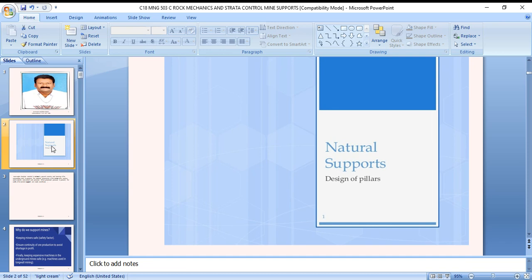The vertical compressive force, the effect of P1, is to compress the rock in a vertical direction, and the strata are not able to expand sideways. There is an induced lateral compressive force along the beds, denoted by P2. When an underground roadway is made in the mine, the equilibrium of the pre-mining forces is disturbed, and there is a redistribution of the vertical and lateral pressures. New kinds of forces also come into play. This redistribution of the pressures is called the pressure arch theory.